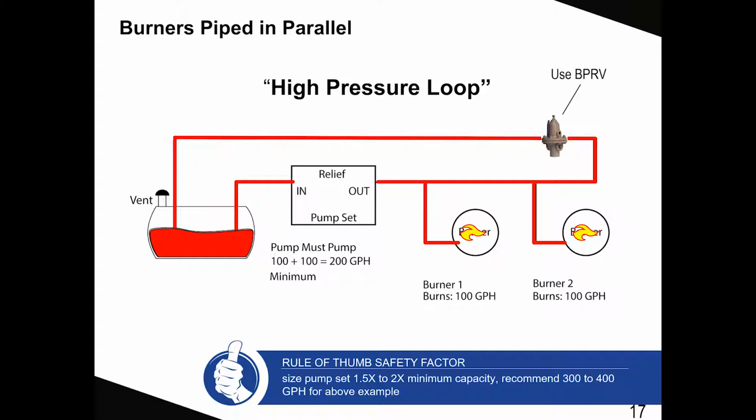So Ed, I wonder if anybody's asking, how come there isn't a return line off of those burners back to the oil tank return line? Well, since there's no pumps on there, we're not pumping more. We're not forcing more oil into the nozzle of the burner. So therefore, there's no oil to be returned to the main fuel oil supply pipe. There are occasions though where they actually will put a scavenger pump on there when a burner is being pulled out of service. They can just pump the residual oil out of it.